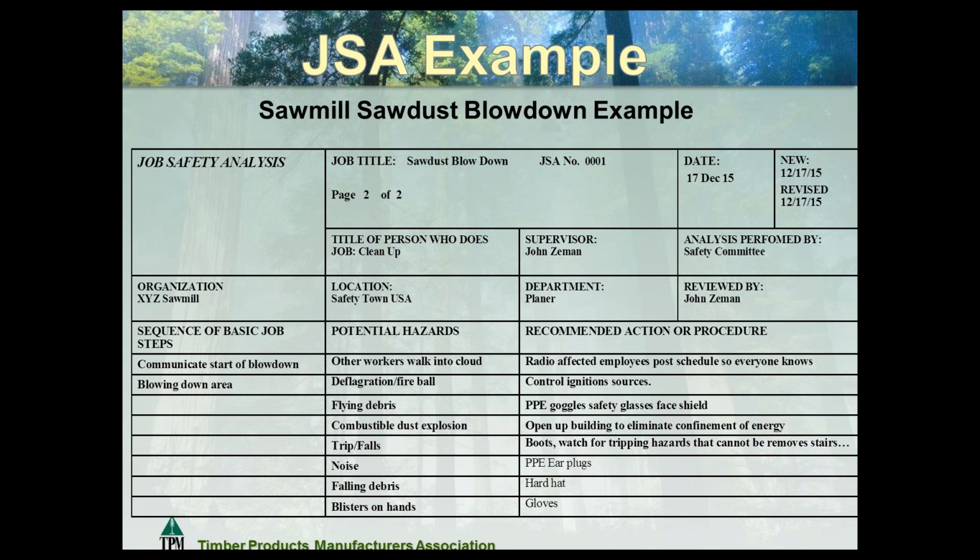There's also some tips out there that not only will they be legal as far as the 30 PSI coming out the end of your wand, but they're also quiet, because there's nothing like an open-ended pipe for loudness, right? So there are a lot of different technological advances out there. And then falling debris: if you're blowing stuff off rafters, ceilings, stuff like that, stuff may fall down. So make sure you're wearing your hard hat.